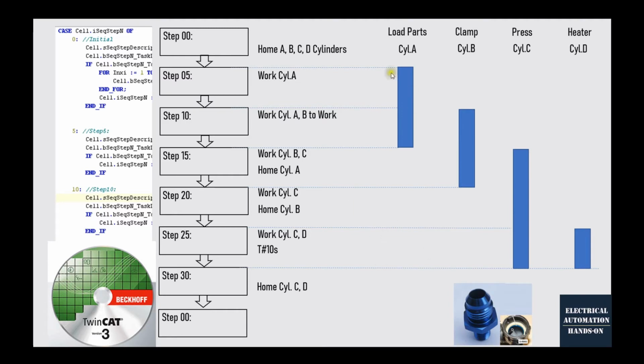And after this, to allow the cylinders to be controlled automatically, we will connect the conditions from this step sequence with the valve bank. Connect the automatic conditions to this cylinder's automatic control. Basically, it allows these cylinders to be controlled by this sequence number. There will be two main parts. In this video, I will mainly talk about the left part, that is the sequence structure. And in the next video, I will discuss how we can combine the step number to control the valve banks.